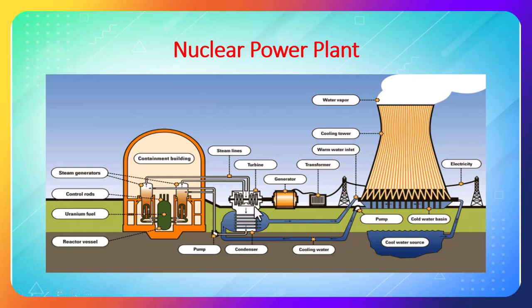Now, after passing through this steam turbine, steam is being brought out. You will have a condenser. You try to condense it, and further if you want to reduce the heat, I will have this structure called a cooling tower. In a cooling tower, against gravity we allow the water to flow, which means we take this hot water to the top of this chimney. From there we flow the water. What happens is the air flows in the opposite direction. Air will move from bottom to top, whereas water will flow from top to bottom. So you get more contact and it cools at a faster rate.